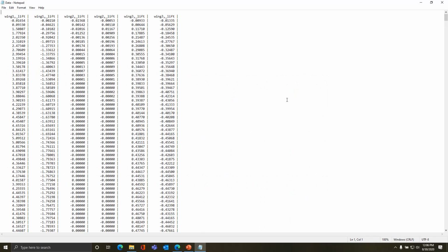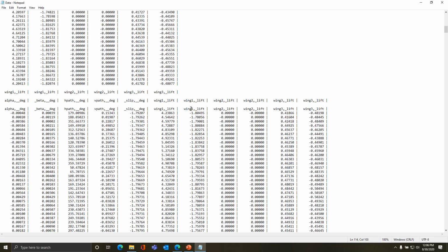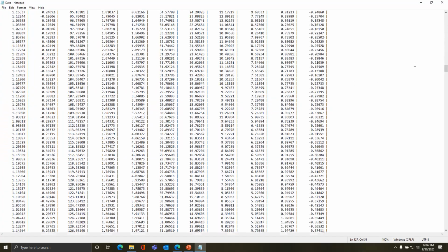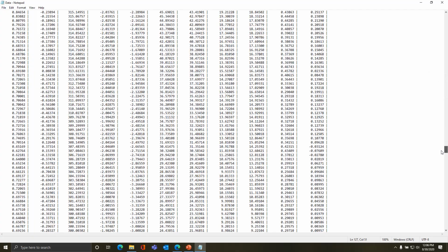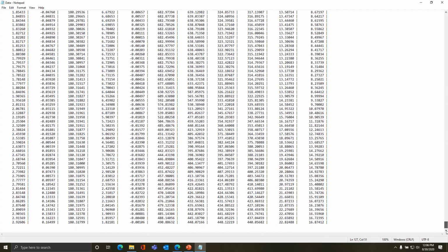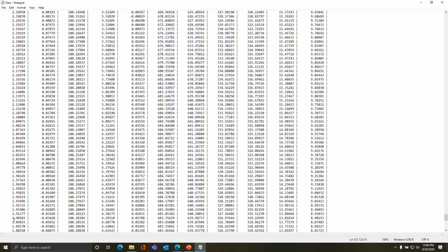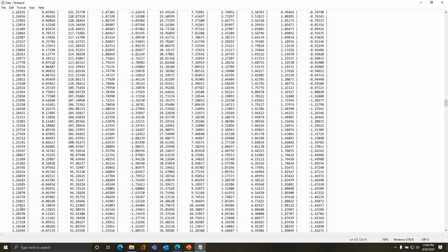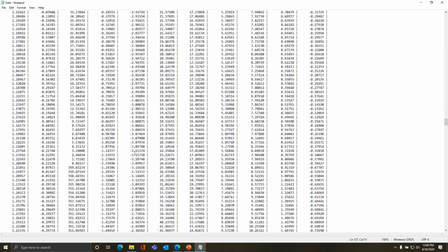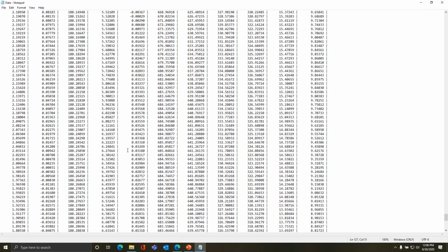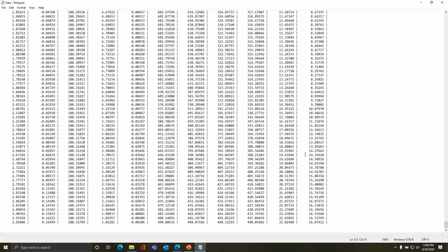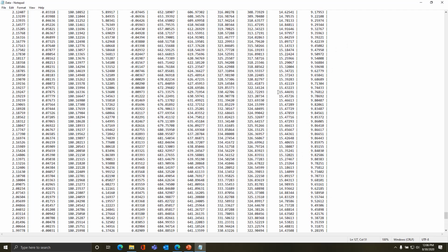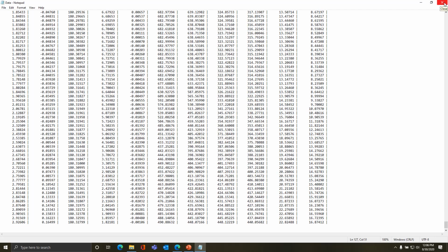Okay, so in the middle of the file, I added the angle of attack. That's why you see it is added in the middle. You can actually change the sample rate, so you will end up with a smaller data set, which is, I think, a very reasonable and good assumption. You can see the angle of attack has changed from 0, and it is changing regularly, and your lift is also changing. Okay, so this is something that you need to do in the lab. You need to go over and essentially compare the modified and the unmodified one.